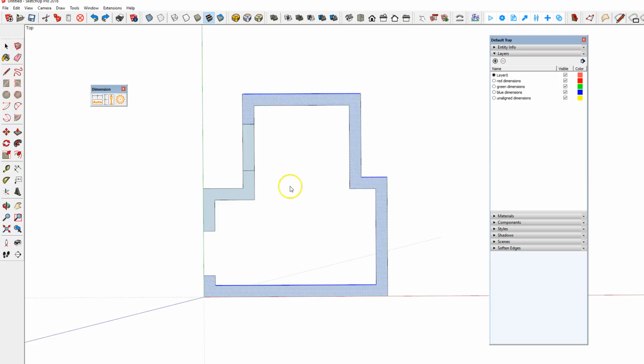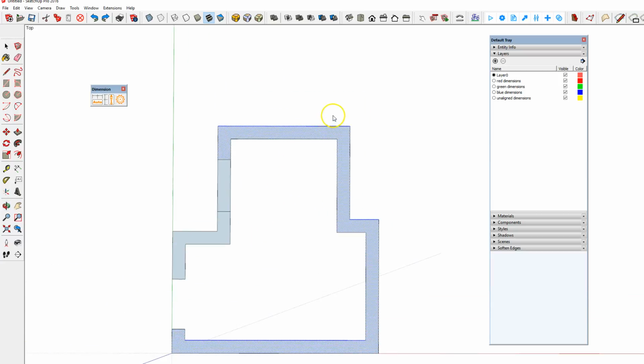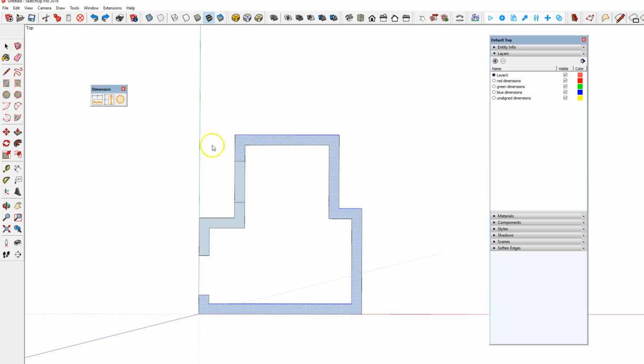So that's using normal geometry. I already mentioned aligning the geometry. I'll do it one more time just to show you. If I select this line and this line and click that, but now I want these measurements to be aligned, I just need to press the minus sign and press enter, and that will align it to the most extreme one.